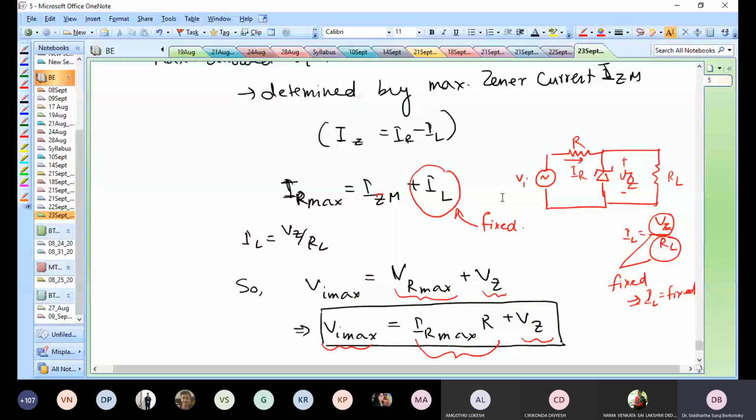Everything comes from very simple principles. The thing about electronics is that most of these analyses just use some very basic approximation to a diode, so everything becomes rather straightforward. You just see whether the diode is forward bias or reverse bias. If it's reverse bias, it's open circuit. If it's forward bias, it's closed circuit.